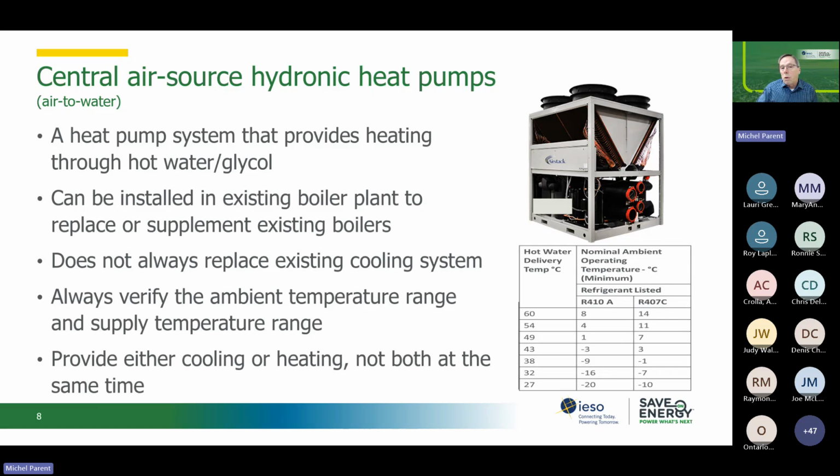It's often used for heating purposes, where you still have a chiller that provides cooling. So it's a heat pump that can actually work in a single mode, but it can work in both modes and provide your building cooling. But it is one at a time. It does not do simultaneous heating and cooling.